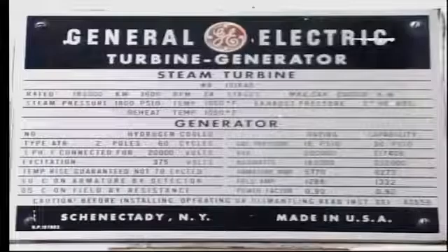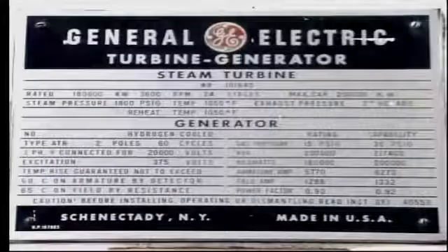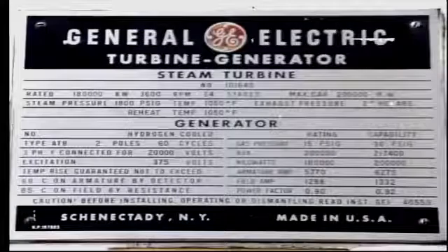In other designs, the shaft-driven fans are made larger to avoid the need for a separate air circulation fan. With this arrangement, makeup air is drawn in through the generator housing by these fans. Well, so much for air cooling. Let's now turn our attention to hydrogen-cooled generators.